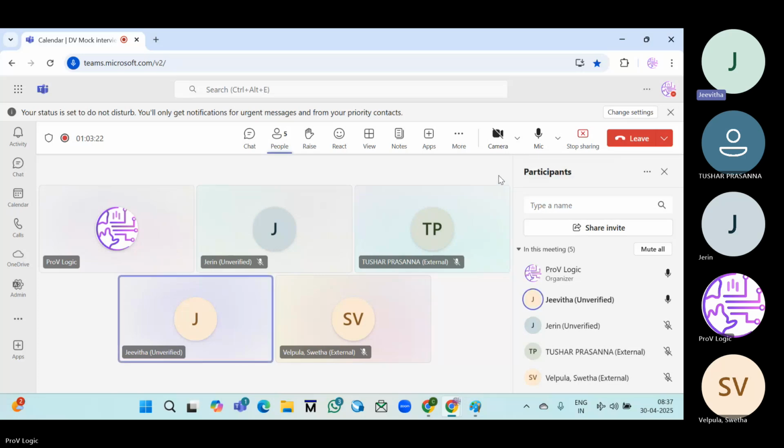In full case, we have to specify all possible conditions with a default also. In parallel case, only one case item will match with the case expression. Otherwise, overlapping occurs.